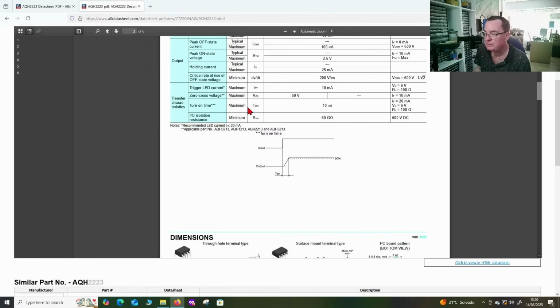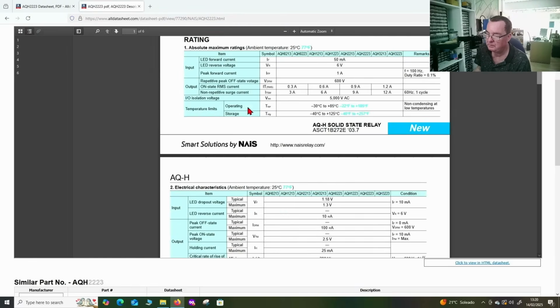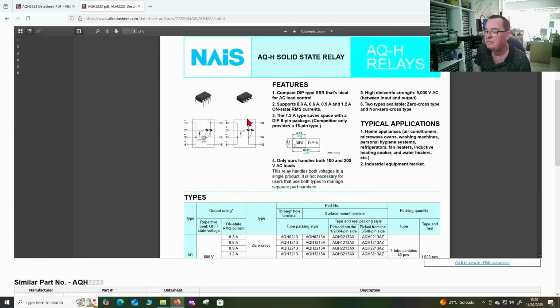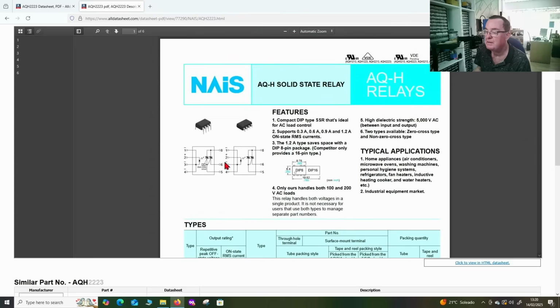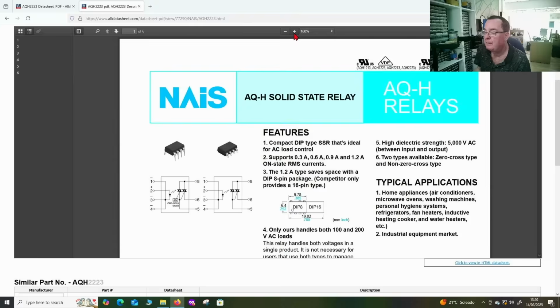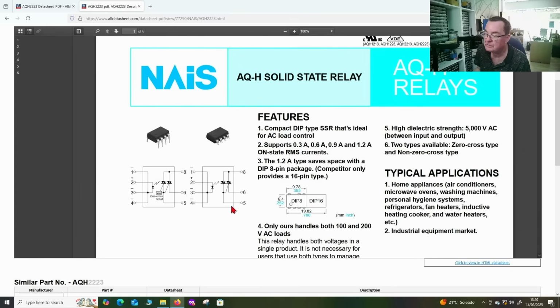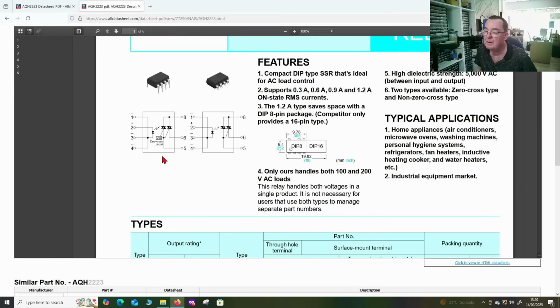That's why I don't see a transformer there, because it isn't a power supply, basically. It has 2 triacs in, activated by an LED. Yeah, a zero crossing detector, so it's only switched when the mains goes through 0.